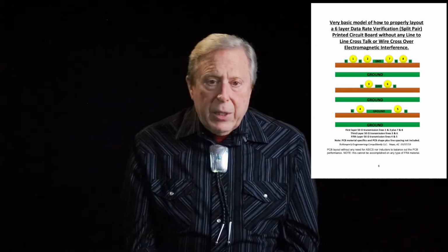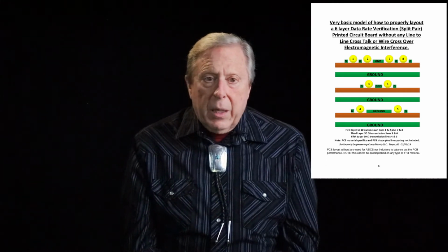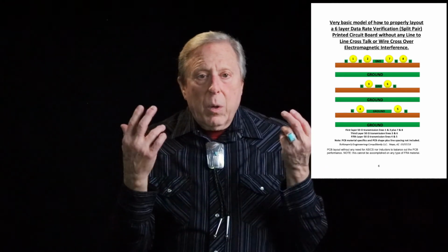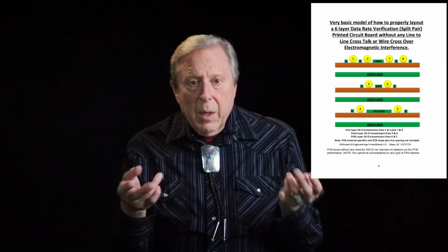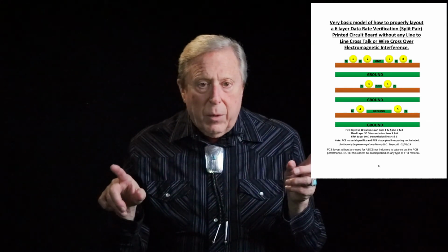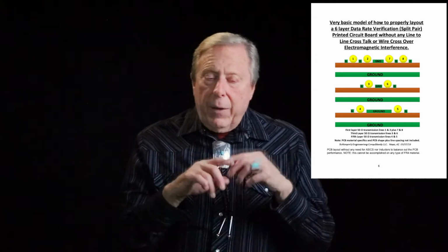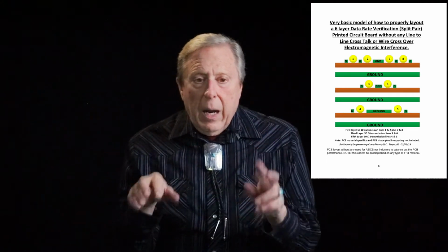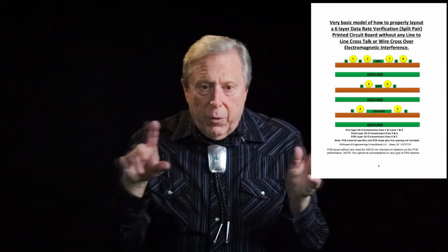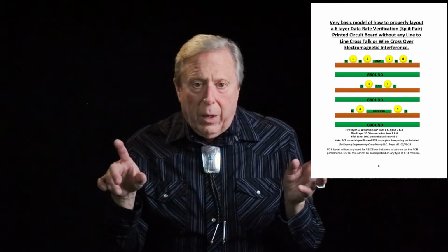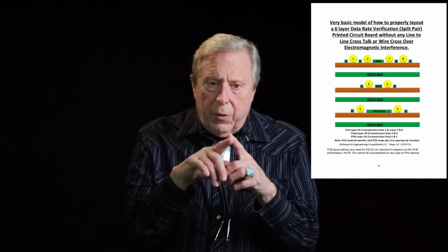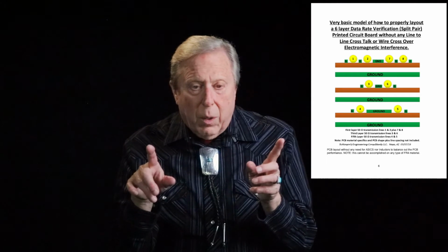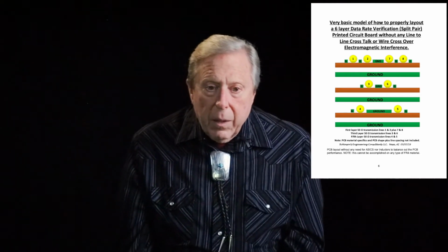And you're going to need a 6-layer board, and the reason why I'm saying that is the top layer will have four paths. Then there will be a chassis ground or earth ground. You'll have another path for 2 wires to go on, and then another chassis ground or earth ground, and then you'll have another path for 2 more wires to go on, and now you have ground.